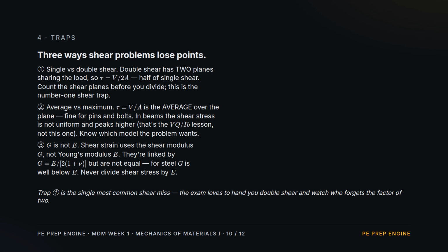Traps. 3 ways shear bites. 1. Single versus double shear. Double shear splits the load over 2 planes, so the stress is V over 2A, half of single. Count the planes before dividing. This is the number 1 miss.